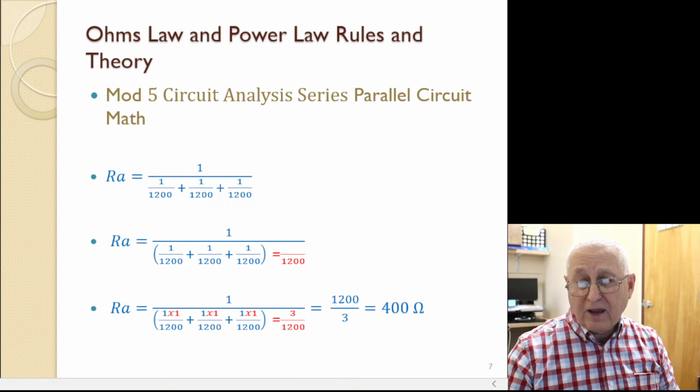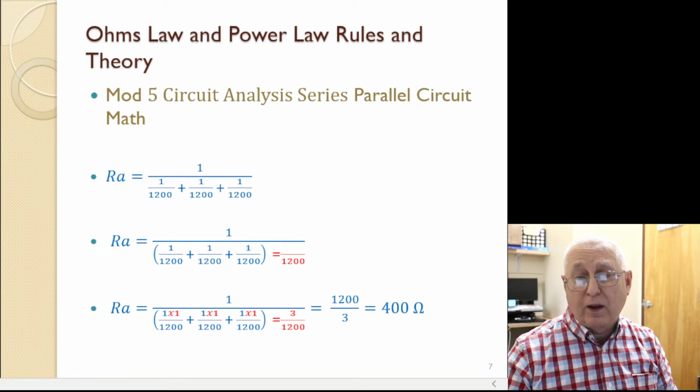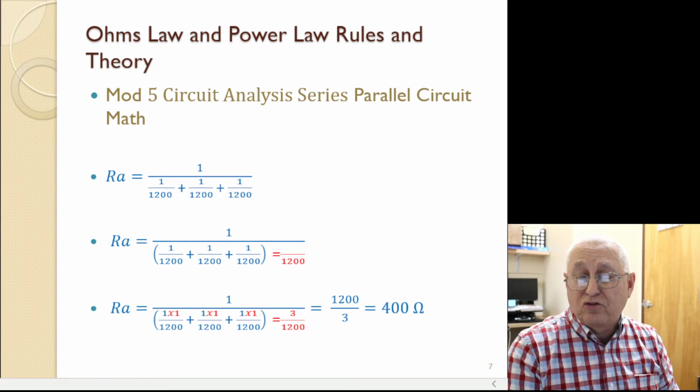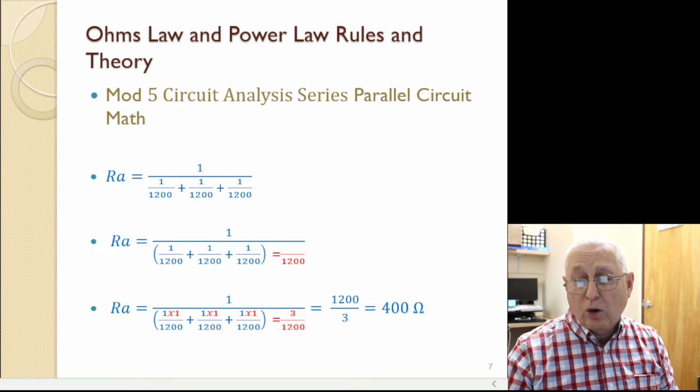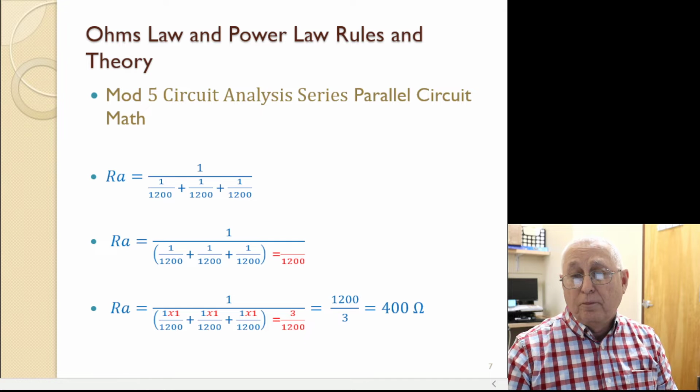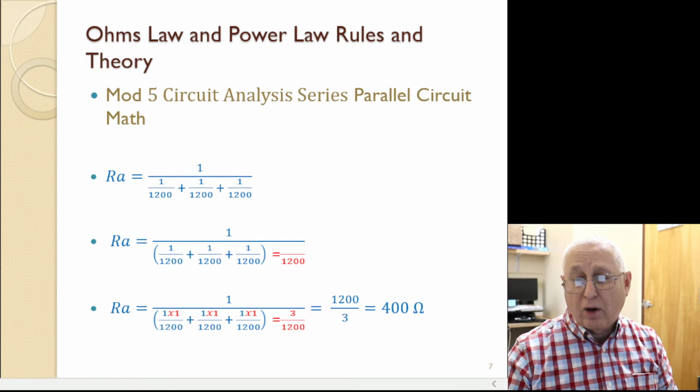Here, in this case, we have the formula for a resistance in parallel. We must use the formula because we have no idea what the voltage drop is going to be across those parallel resistors at this point, because it's determined by the R1 and R2 resistors in series, and we have to know this resistor that calculates out to 400 ohms because it's proportional on the drops.